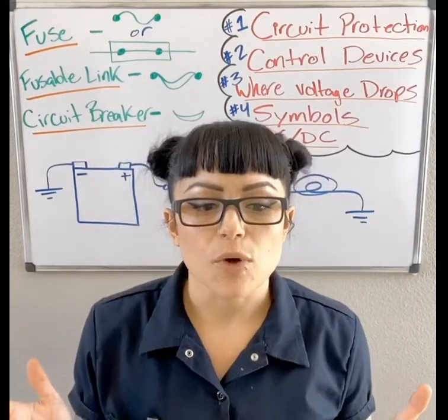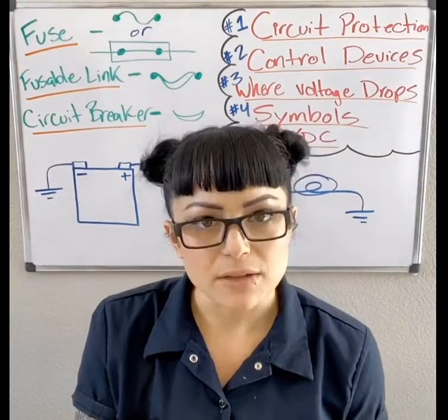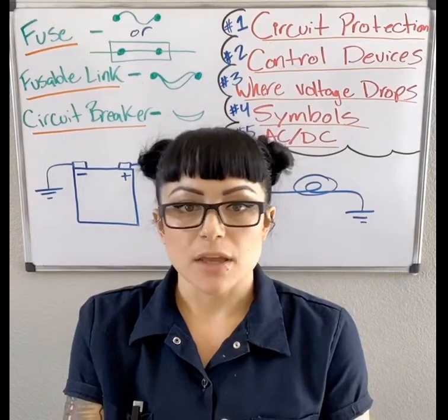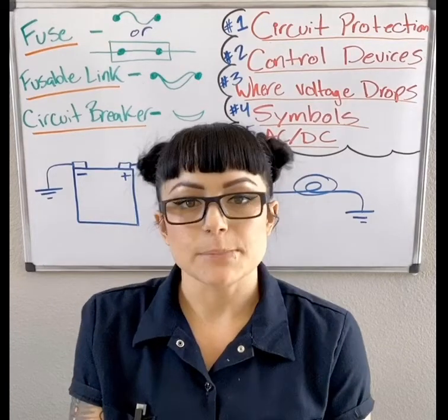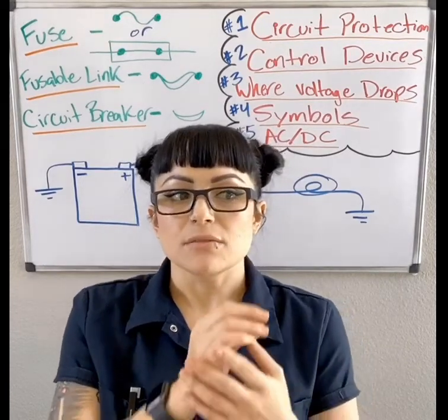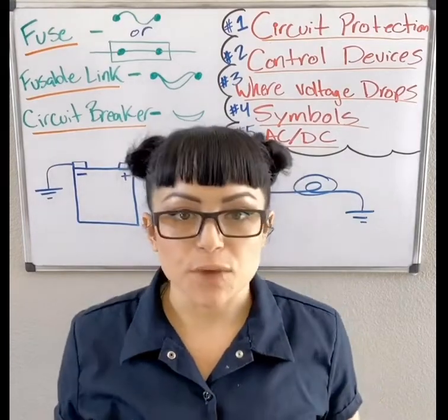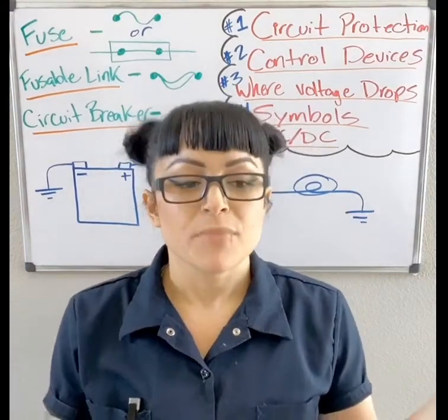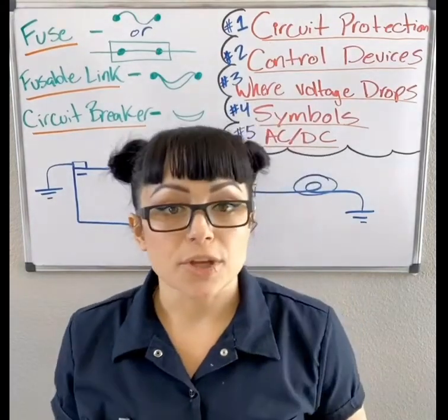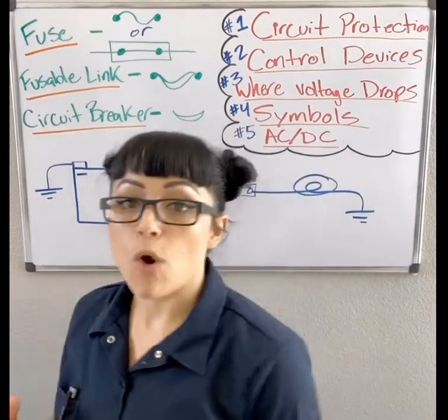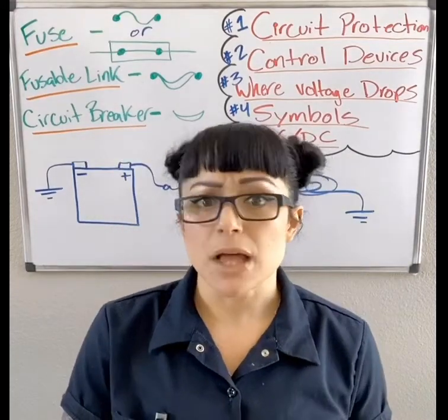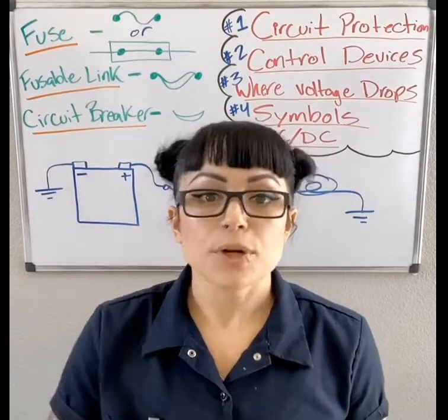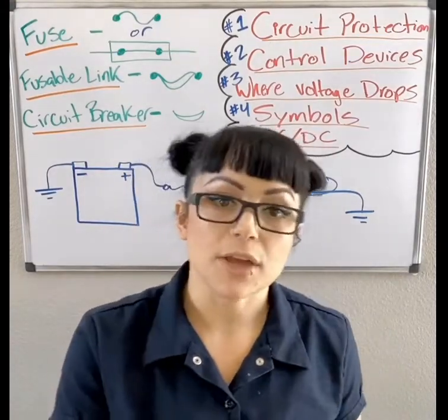And so when the circuit was built, we know the resistance engineered in that circuit of the motor, of the light, whatever it might be, and we will fit the rest of the circuit with the gauge of wire that is needed. You will find starter circuits are going to have a whole lot of amperage flow because of the mechanical resistance involved, but high amperage flow circuits are going to require thicker gauge wire.